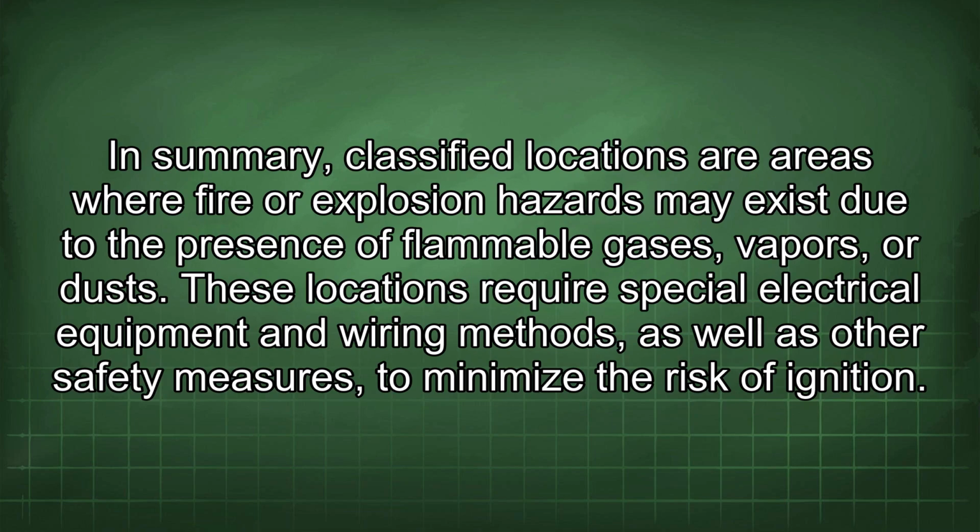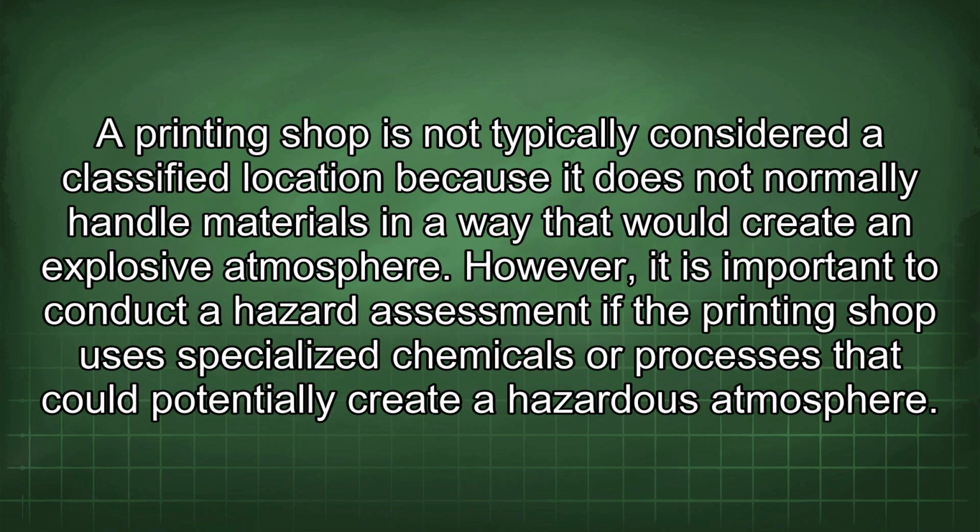In summary, classified locations are areas where fire or explosion hazards may exist due to the presence of flammable gases, vapors, or dusts. These locations require special electrical equipment and wiring methods, as well as other safety measures to minimize the risk of ignition. A printing shop is not typically considered a classified location because it does not normally handle materials in a way that would create an explosive atmosphere.